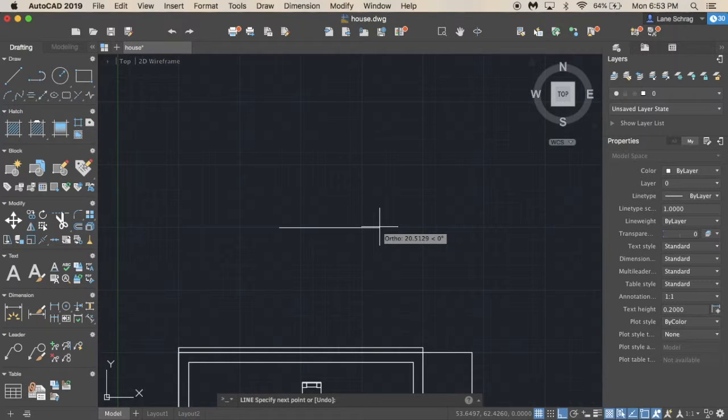line to be 50. Well, that's the thing about AutoCAD, AutoCAD doesn't have a specific measurement with it. You can change it in the settings, but you just type in 50 and it's just 50 units. It's not only in feet, it's not only in meters. You can change what you want for different countries, different projects. If I were to build a case or something in here, I wouldn't want it in feet because that'd be way too big. But for a house, you want it in feet or yards or a bunch of different stuff. You can have it any way.